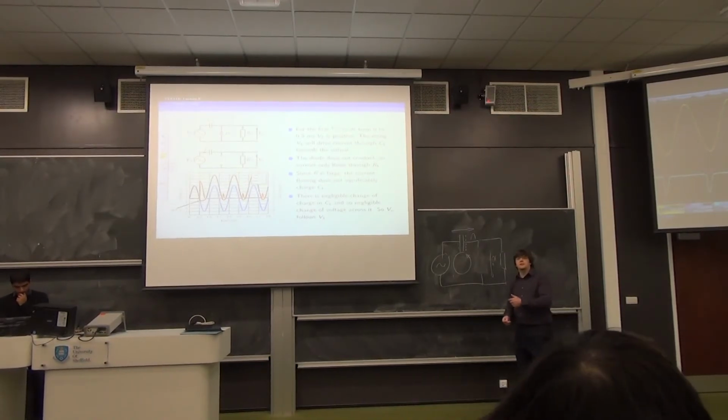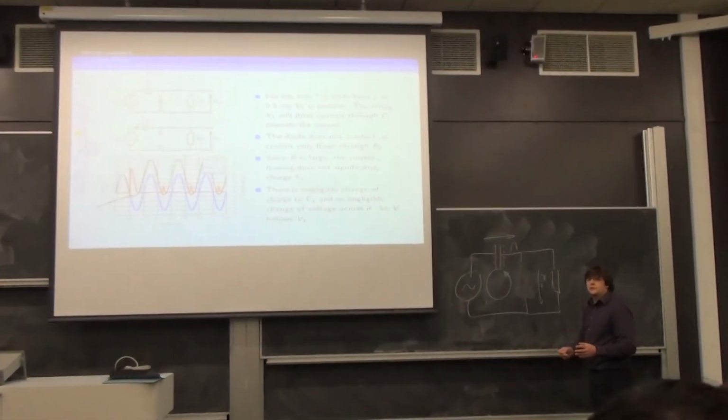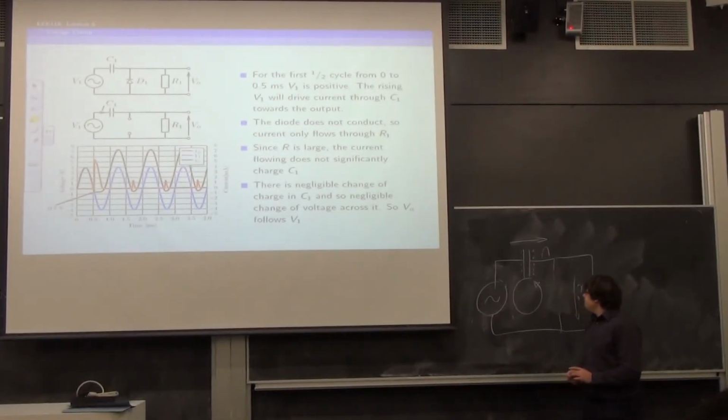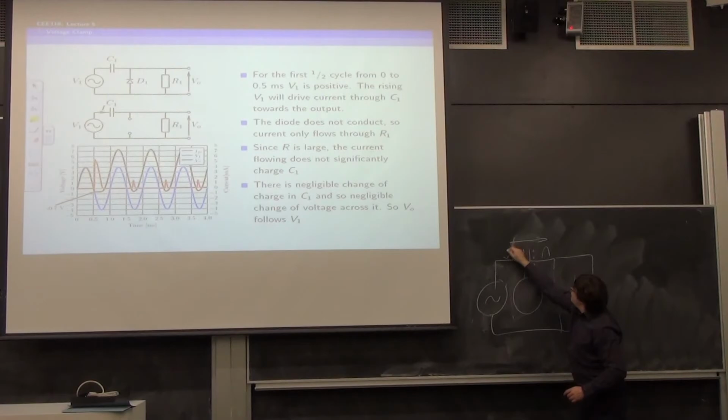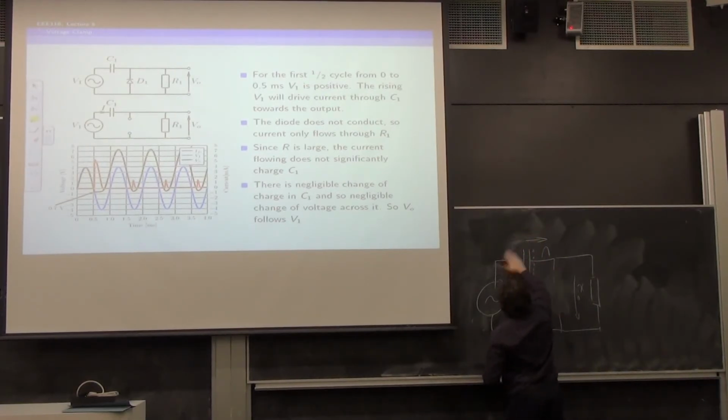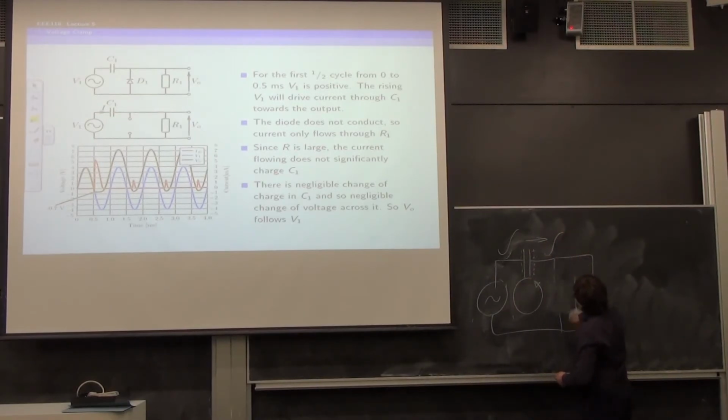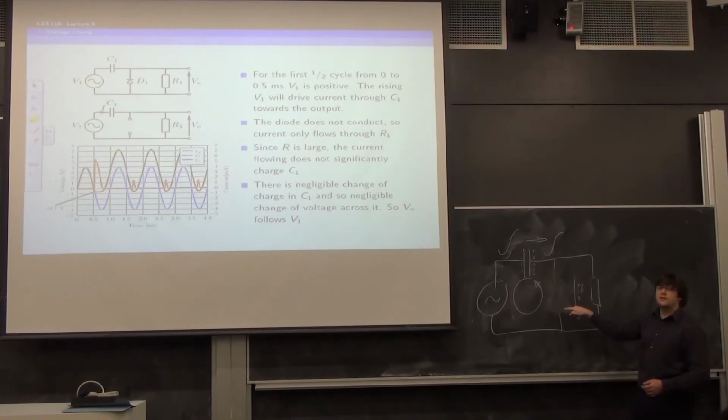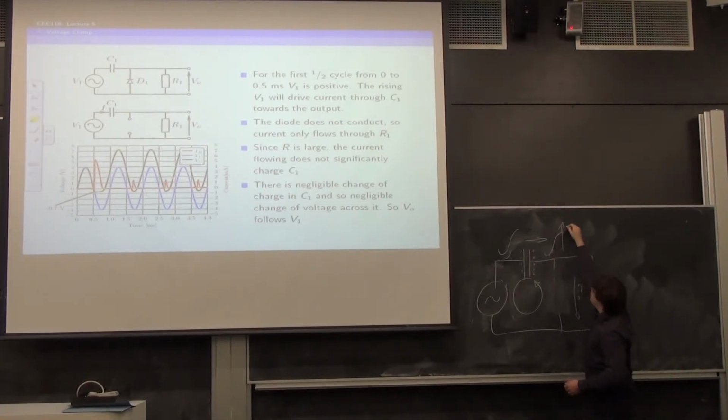I = C dV/dt, where Q is the integral of I. So if this one's rising, going up like that, do it again, like that, this one's doing that, this one must be doing this as well, except that there is now a voltage difference across here equal to the peak value of that minus the 0.7 that we lost in the diode. So this waveform is now shifted up the page a bit. In fact, the lowest part of this waveform must be held at minus 0.7 volts.